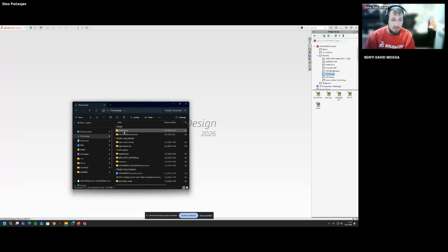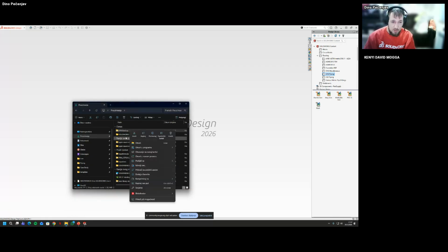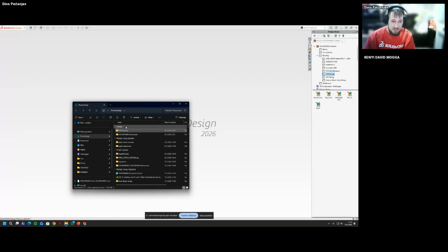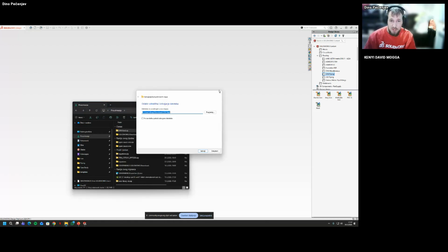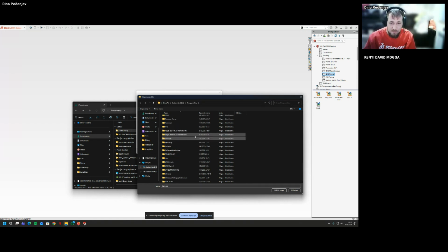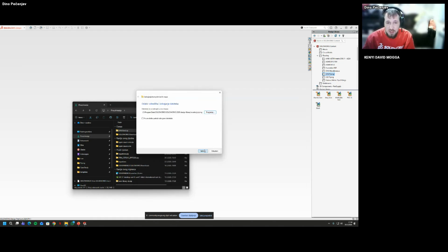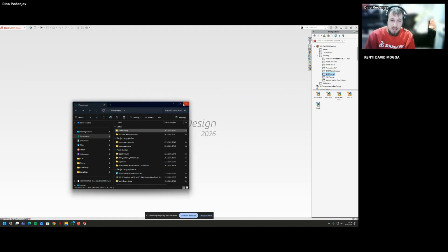Now that it's downloaded, I'm just going to take a look. Okay, we have a steel folder. Why am I looking at that? Because that will be for the last slide. If I go to my routing library location, I can go here, design library, routing, go to piping, choose this location and extract it.